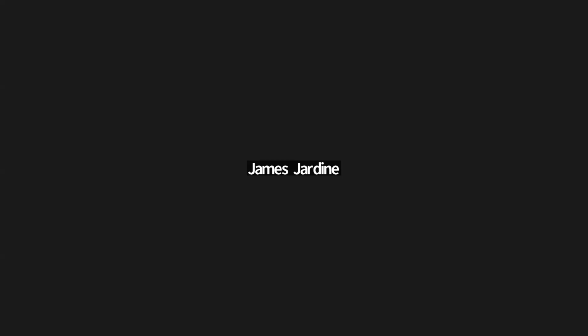So there could be a number of issues there. It's possible that there's been a cut in the loop where they've installed seating and drilled through it. There could be a short if it's a phased array, or a similar problem. If they've not used proper direct burial cable and just used ordinary PVC covered cable, then perhaps the concrete has eaten through the insulation and caused problems there.